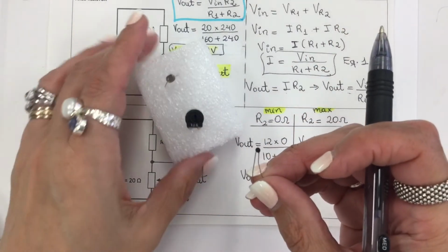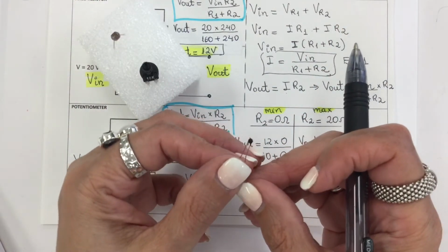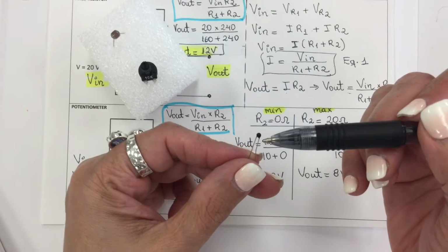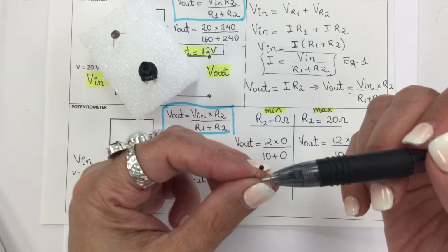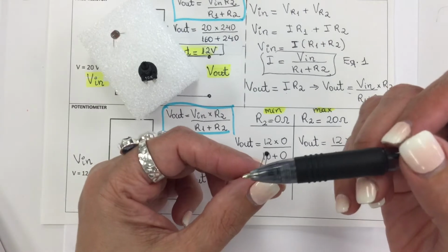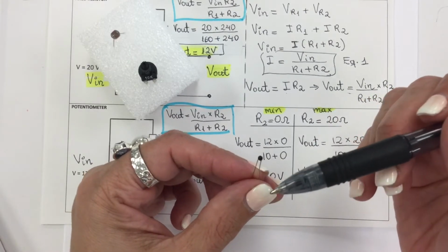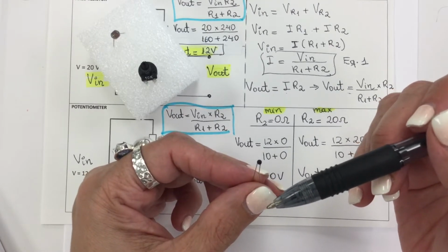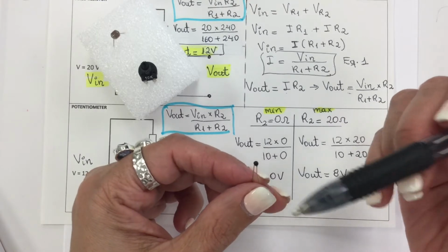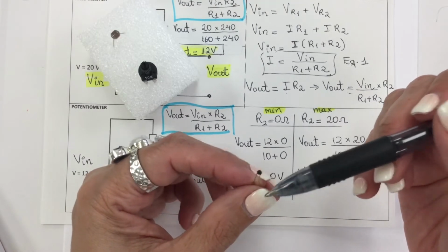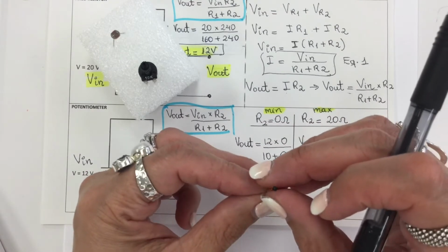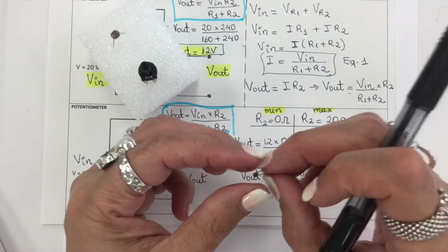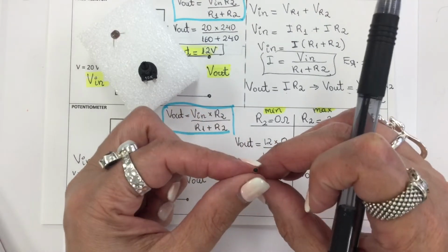This is a thermistor. A thermistor is a resistor that changes its resistance with the temperature. This one here in particular is the NTC thermistor. N stands for negative, T for temperature, and C is for coefficient. So NTC thermistor. This type of resistance decreases as the temperature rises due to an increase in conduction of electrons.